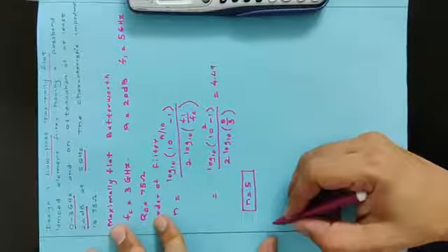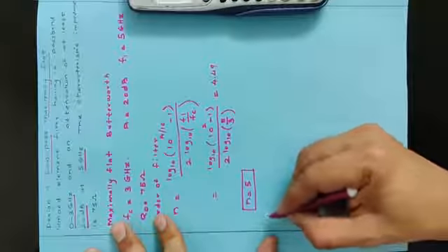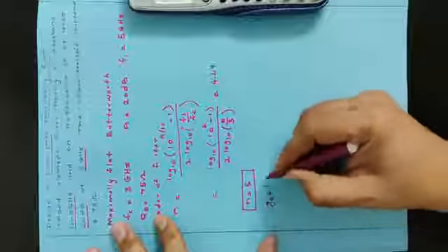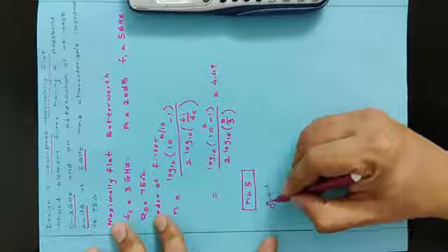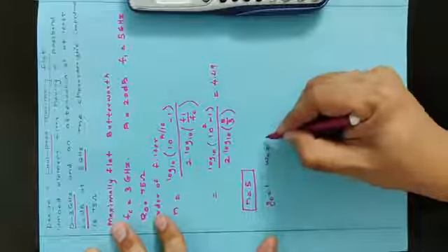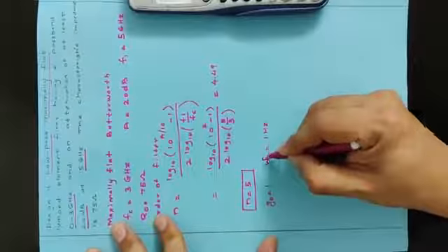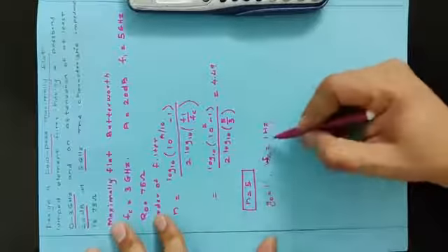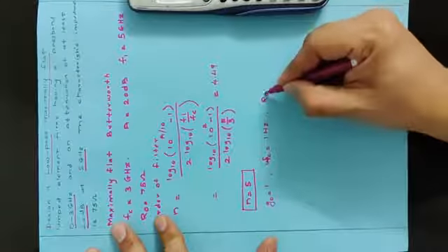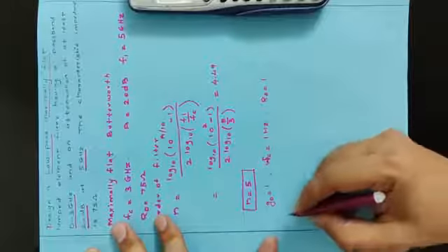Now we have to obtain the coefficients for the low pass filter. These coefficients are given for G0 equal to 1, that is the normalized conductance equal to 1, and omega c equal to 1, cutoff frequency fc equal to 1 Hz. After which we will go for the impedance and frequency scaling to obtain the corresponding values.